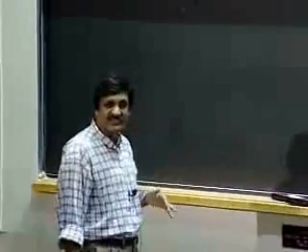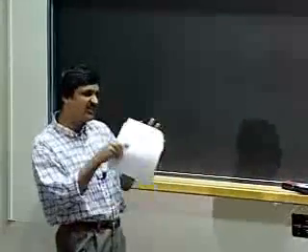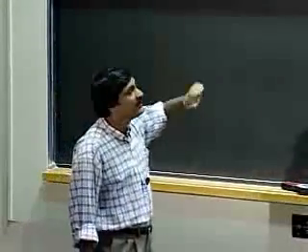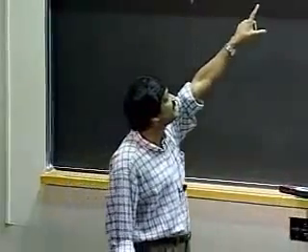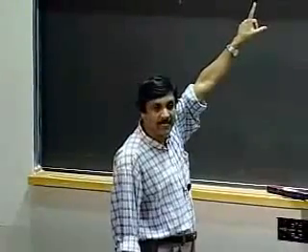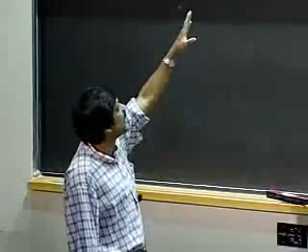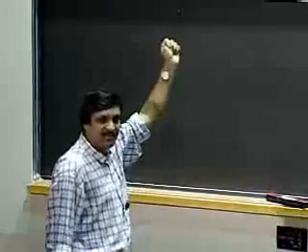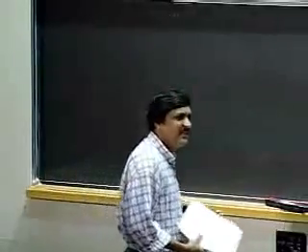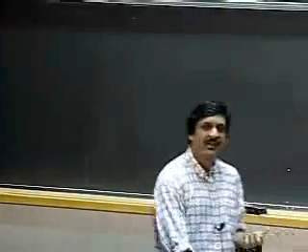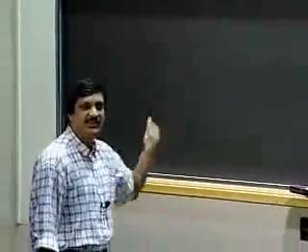Okay, so that's where the insight begins to show that if everything were magical, and I could somehow exactly keep things just so, that will be true. I will be able to build a positive feedback circuit where the output is equal to R2 divided by R1 V in. But remember, even the slightest amount of perturbation is going to send the op amp scurrying off to the positive rail or the negative rail. So how do we analyze that? How do we analyze the behavior of a circuit that, based on a small perturbation, begins to move one place or another?